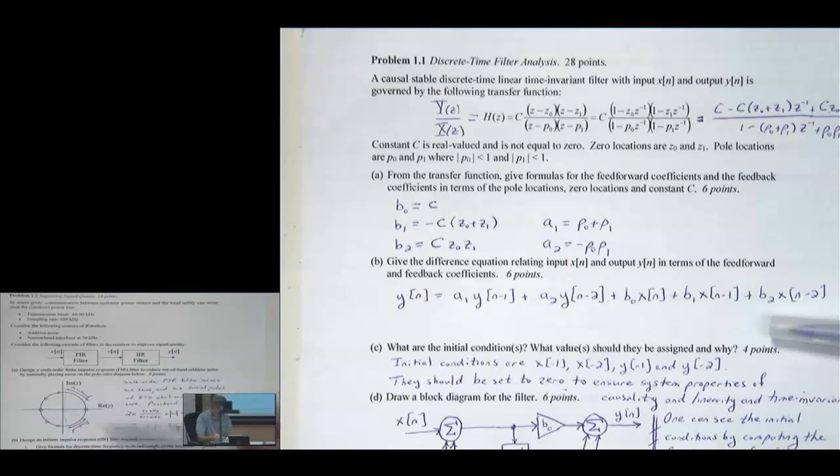Another solution you could have come up with: you could have put 2 zeros around either side of the z equals 1 point, omega equals 0, and you could have put 4 zeros over here. That would have been a pretty good one, too. You just want to make sure you keep the zeros away from the passband, because ultimately our IIR filter is going to have some poles, and we want to stay away from the poles that could be in the passband.